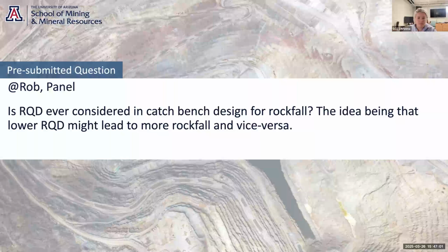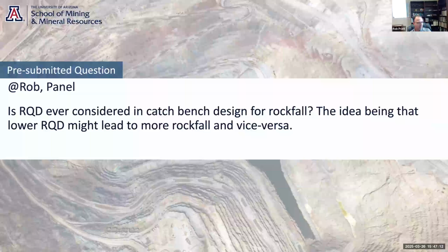And if we have a particular rockfall problem in a particular area that might be associated with bad ground, it could possibly be due to some larger scale issue. Oftentimes, bad ground correlated to RQD could be correlated to rock structure, and in a larger scale problem, basically a slope that's gradually moving on you and that is causing a rockfall problem. And so in that sense, I would say the two are related.